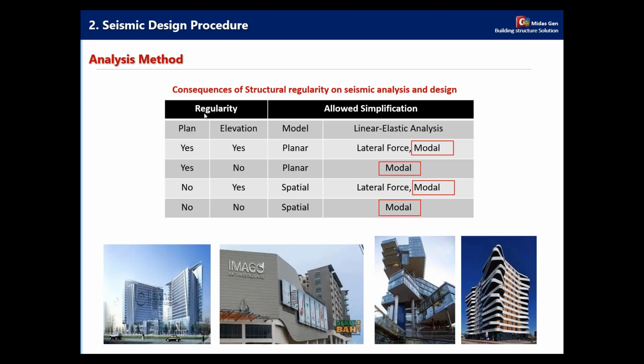But when the regularity in plan is satisfied and the elevation regularity is not, you can use only modal response for the analysis. When the plan regularity is not satisfied but elevation is satisfied, you can use both methods. But when both plan and elevation regularity are not satisfied, you can use only the modal response.